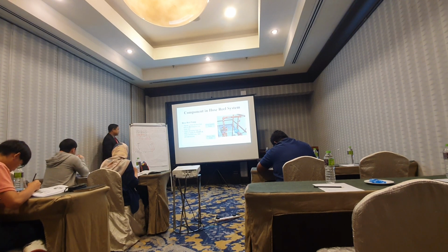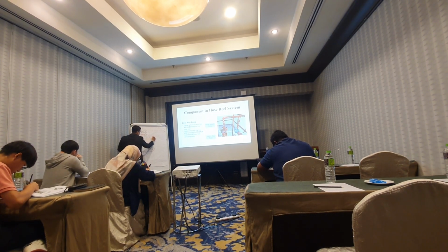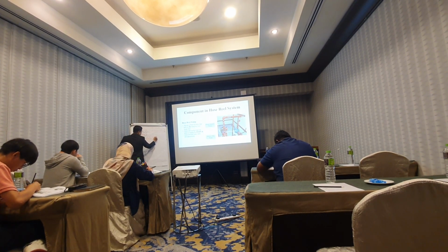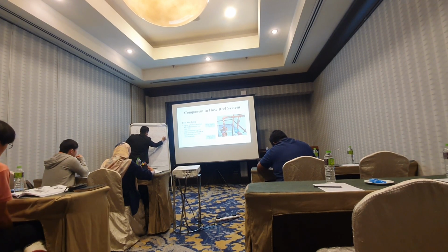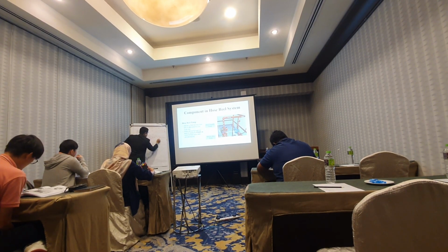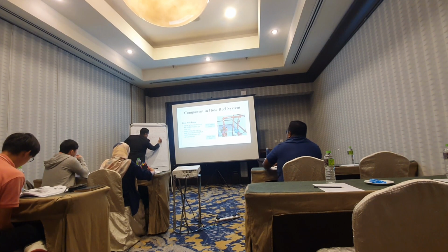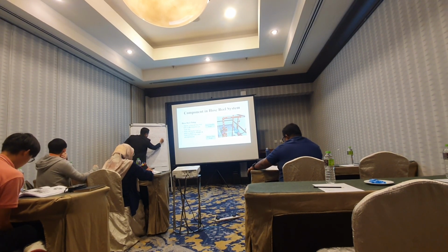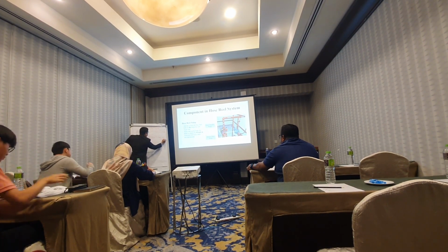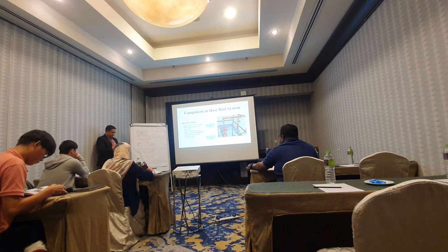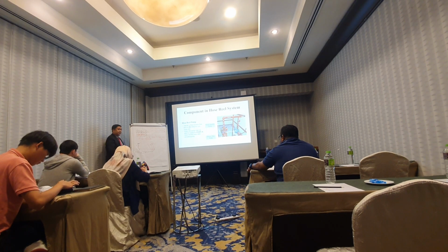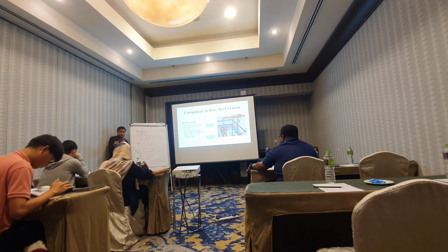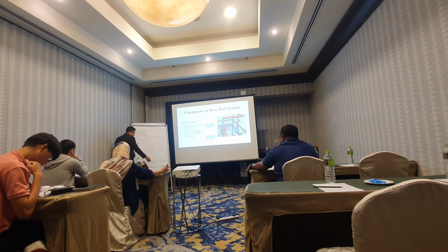For example, if you require 6 hose reels, what is the tank capacity? 10,000? 10,800. Liters, right? Yes, liters. So in the EBBL it is now clear cut. It means if you are expecting more hose reels to operate, then you need to add up the capacity.